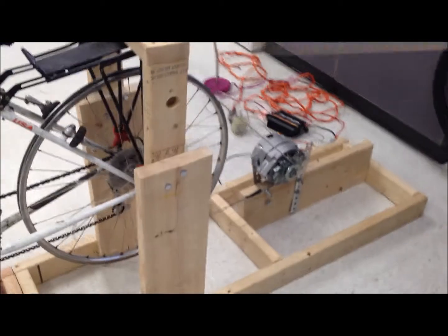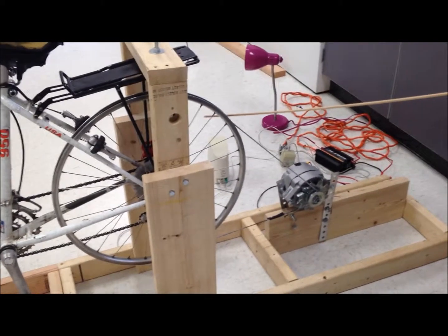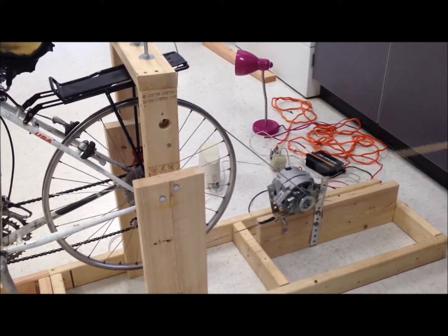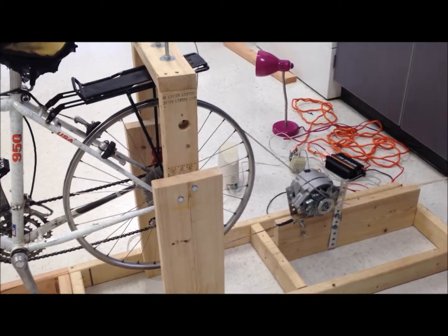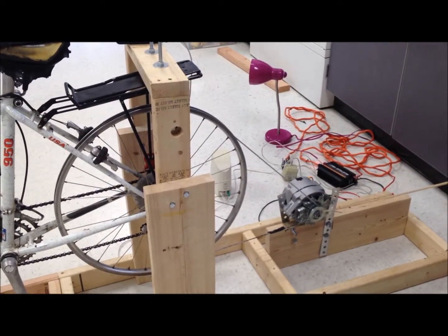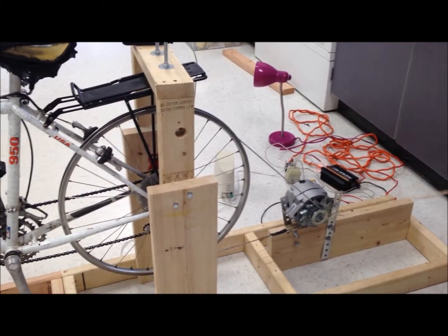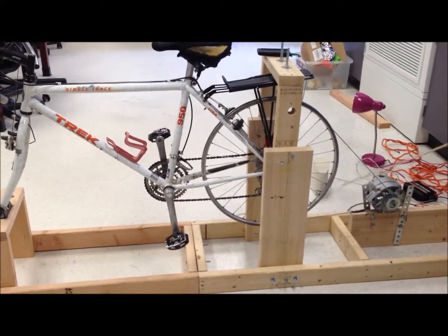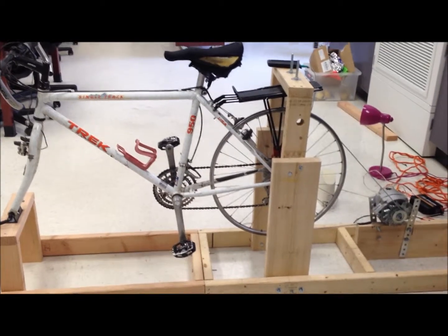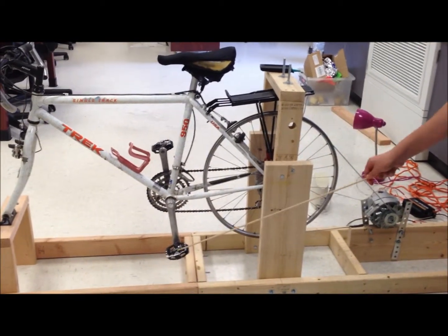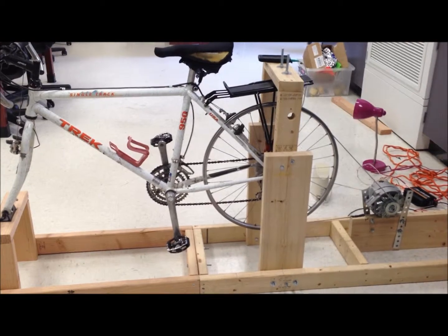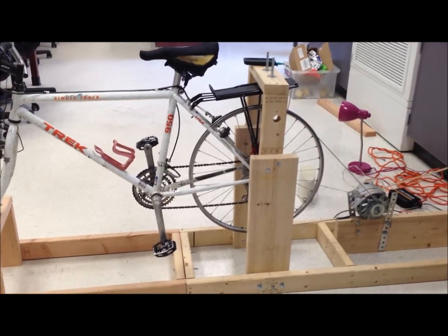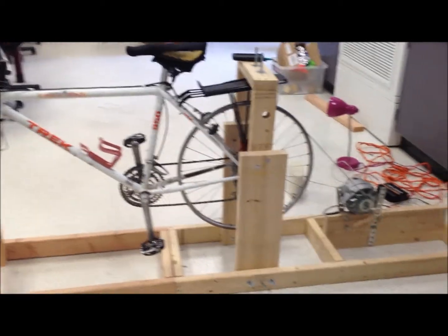The mechanical advantage of the second pulley was calculated by finding the diameter of the rear wheel and the diameter of the pulley wheel. That gave us a mechanical advantage of 10. The total mechanical advantage of the system equaled out to 30. This was found by multiplying the separate mechanical advantages 3 and 10 together. So for every one time someone pedals, the alternator will spin 30 times. This enables the bicyclist to reach the needed RPM to turn the alternator.